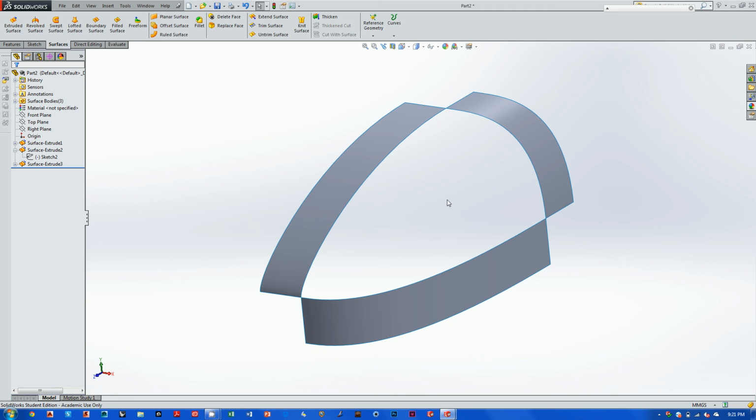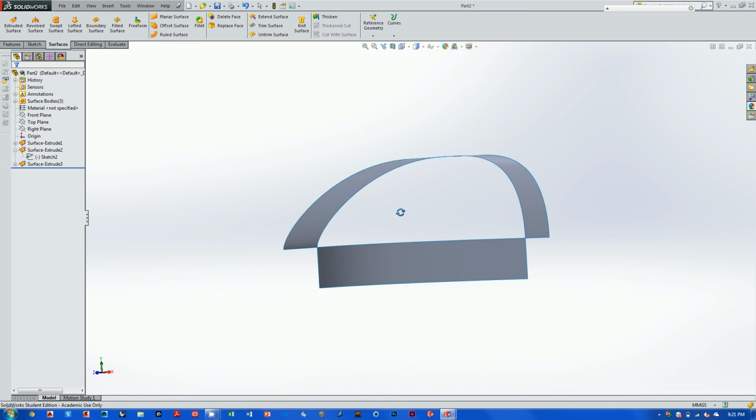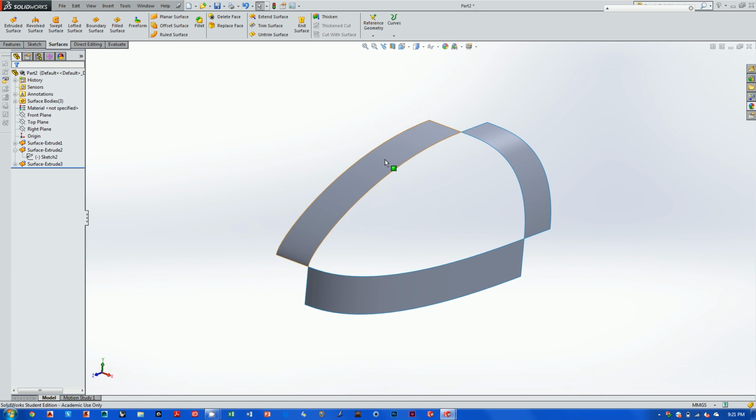Okay, I'm going to call this video right here and just stop it right there because I really want this concept to sink in. The concept that I'm discussing right now is the idea of creating reference surfaces. That's each one of these surfaces right here. What these things are going to do, we're going to hide them later on. We're not actually going to see them in our model. We're going to just use them as something we can line up our surface fill to, something we can attach it to so that we can achieve perfect curvature continuity across our parting line.